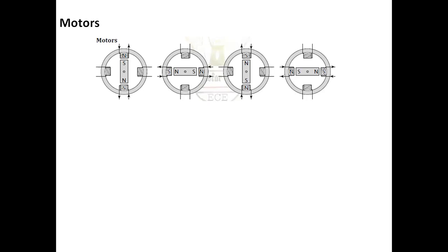Apart from the normal DC motor and the stepper motors, we also have something called a servo motor. These servo motors are able to provide continuous rotation, and the motor itself can be a simple DC motor where we have an applied voltage. This applied voltage determines the motor's speed, and the polarity of the applied voltage determines the direction of the motor. The servo function of the motor involves the use of feedback. This feedback is basically used to control the position or the speed of the motor.